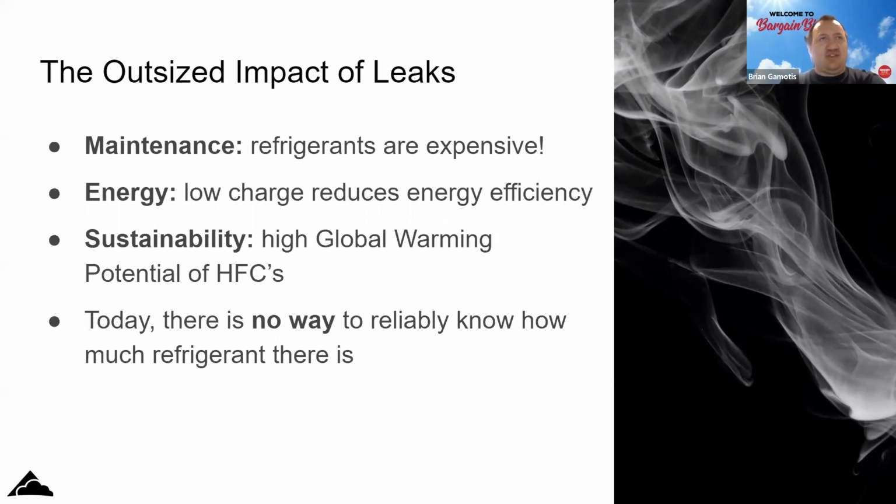Those are extremely rare. Usually you're in for a good hunt to find the right leak and find where it's coming from. And if all you found on your first leak check was a Schrader core, odds are you didn't actually find the leak. So just walking into a store and knowing that you need to be patient and thorough, and keep at it until you find it.